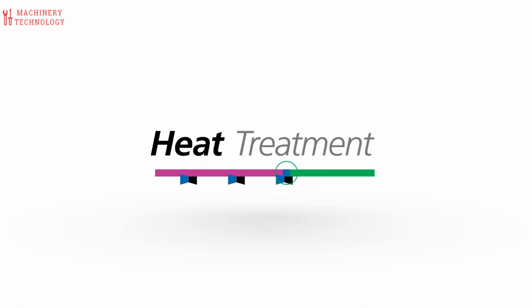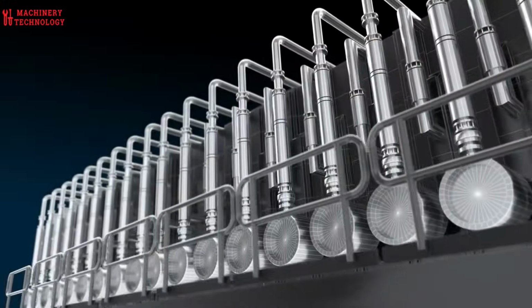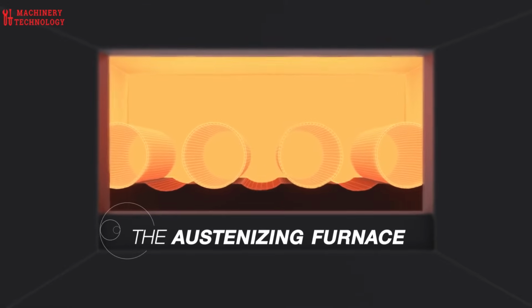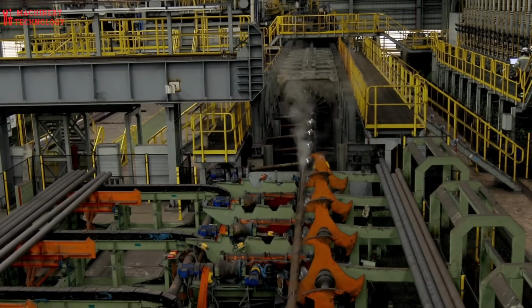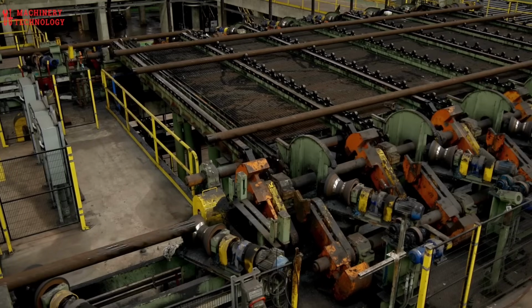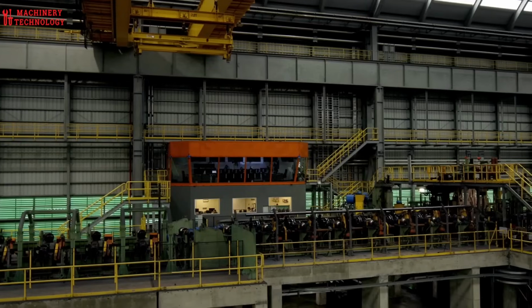The second important step is the heat treatment process, which ensures the hardness and toughness of the steel pipe. Starting from the furnace, where the pipe is heated to a higher temperature, it then enters a cooling process where water injection is used to accelerate the pipe from about 900 degrees Celsius to ambient temperature, causing rapid phase change in the steel. As a result, the steel tube is very strong and brittle.